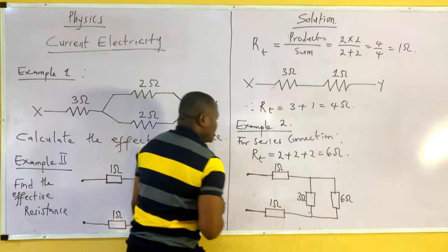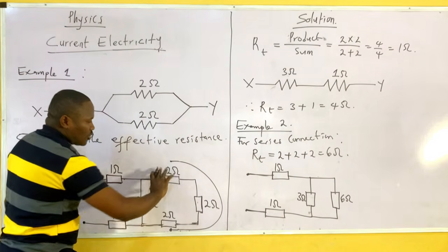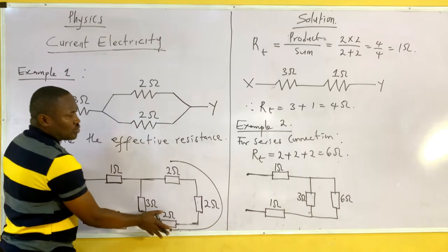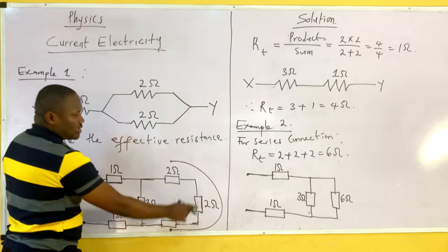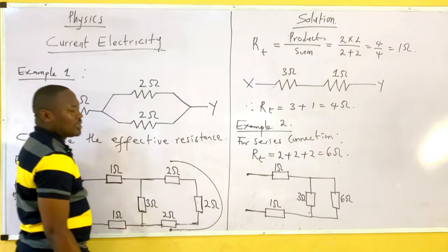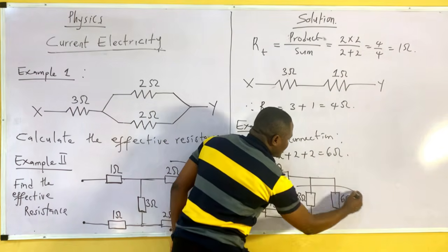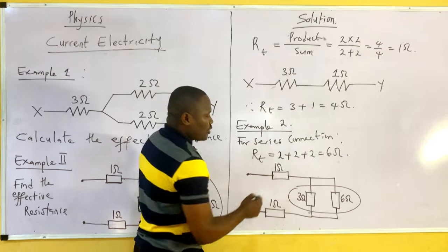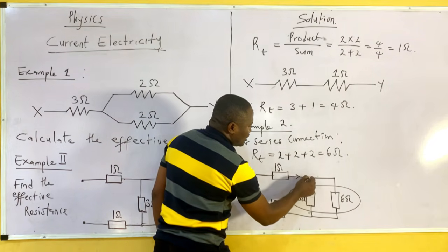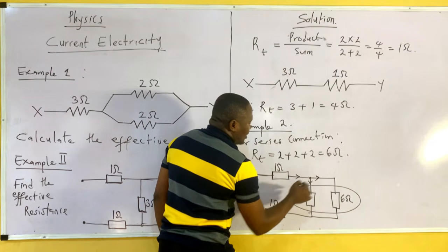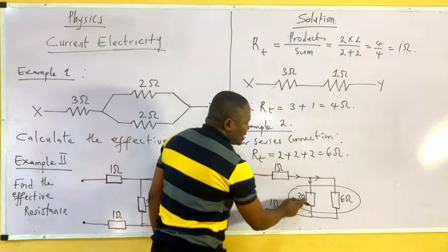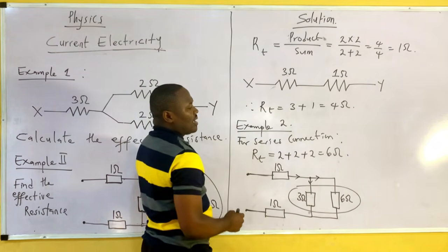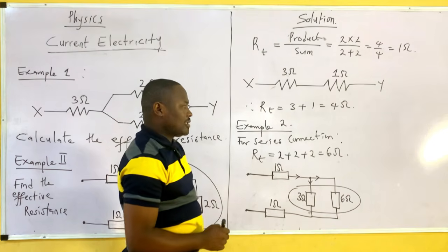So you see the new circuit. Everything about here has been closed because it is in series to now become 6. So now this and this are in parallel, not in series. Because if a current is coming from here at this junction, it will divide, while it will go this way. So 6 and 3 are in parallel, not in series.